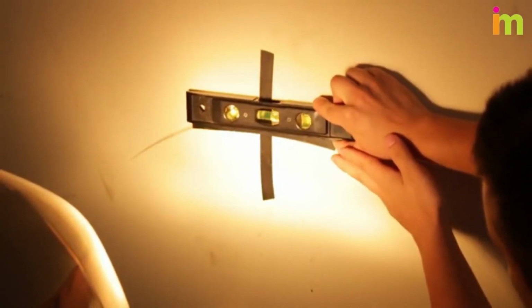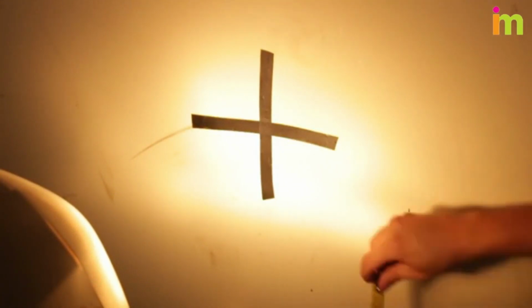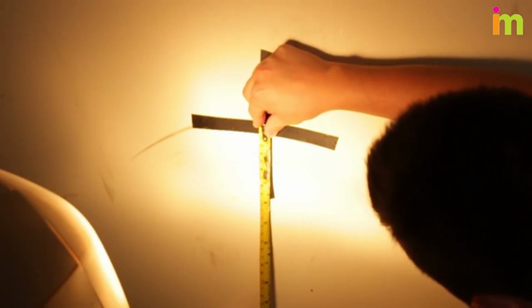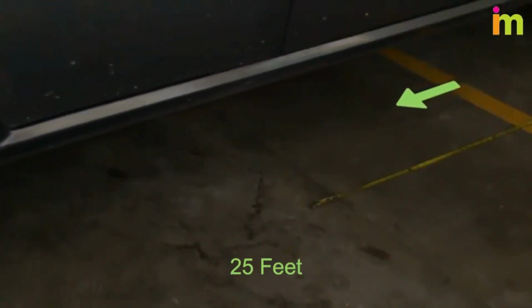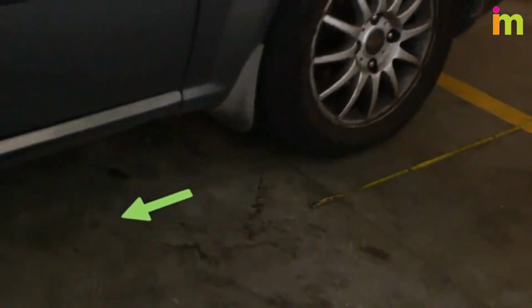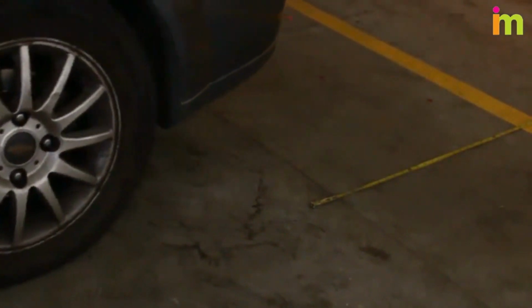Place a spirit level between the two marked center lines to see if they are even. If they are not even, use a tape measure to measure how far up the wall the lower mark is and lower the other center line marker to the same height. Back your car exactly 25 feet, 7.6 meters from the wall. Some manufacturers recommend different distances for proper adjustment, although 25 feet is the most common distance.